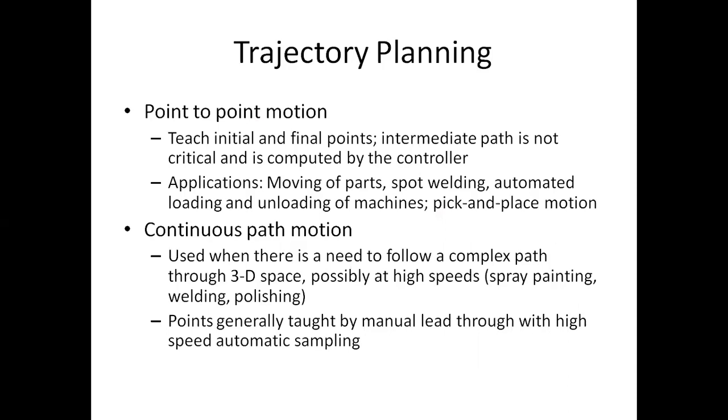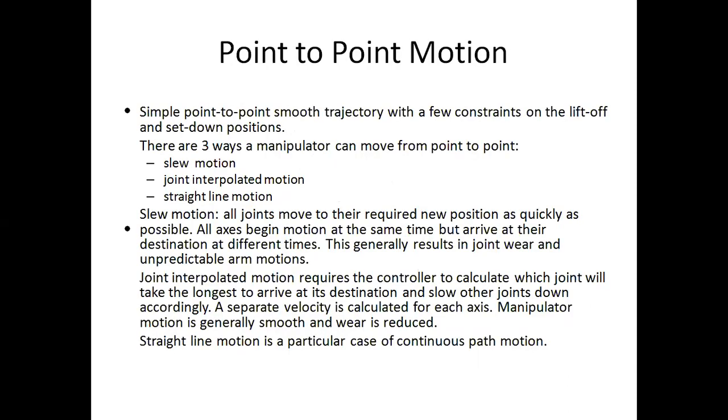Applications include moving of parts, spot welding, automated loading and unloading of machines, pick and place motion. Continuous path motions are used when there is a need to follow a complex path through 3D space, possibly at high speeds. So points are generally taught manually, through which high speed automatic sampling occurs.